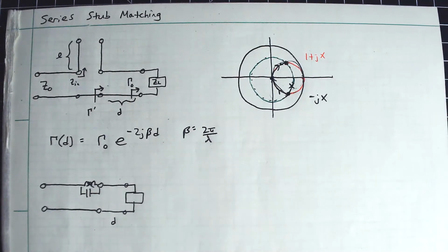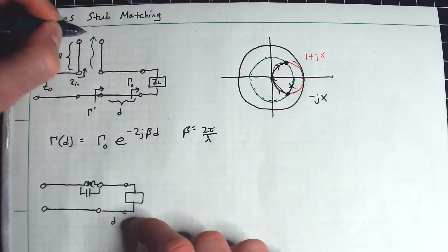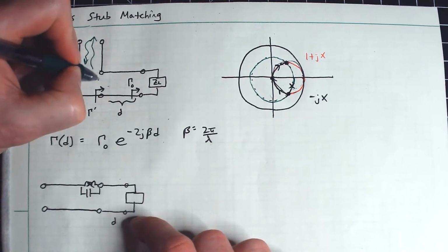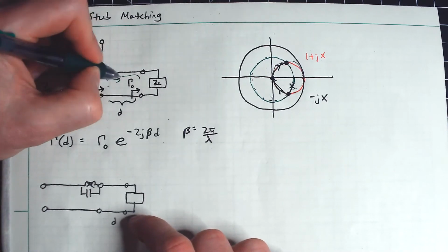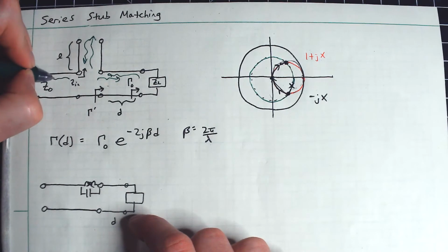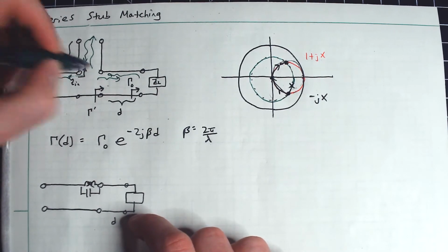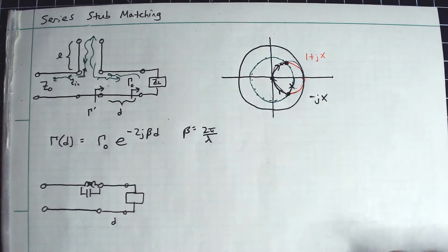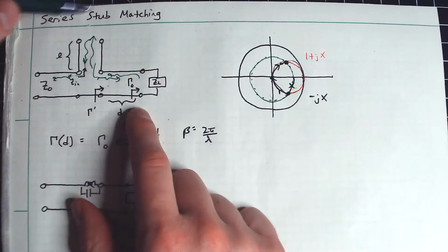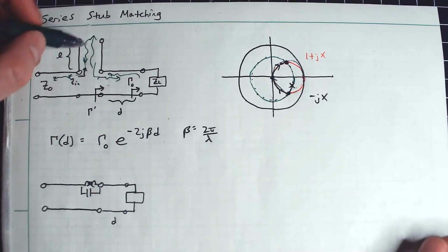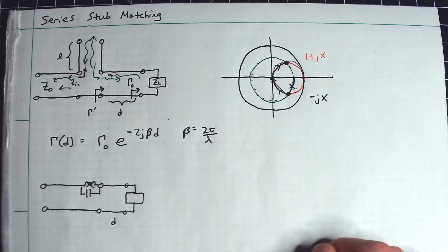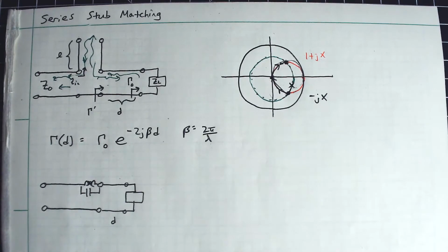So one way to think of this intuitively is you imagine there's a signal going down here, it strikes the end and it bounces back, and then I have a signal going down here which strikes and comes back, and then there is some net reflection here where this is going to transmit down and again. And everything is all adding up as superpositions. And if you tune these lengths just right, essentially what's happening is these two waves that come together and create a transmission back in the opposite direction, they are destructively interfering.